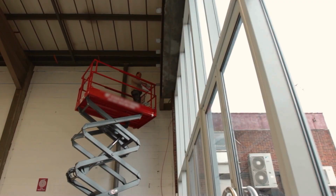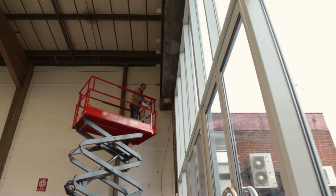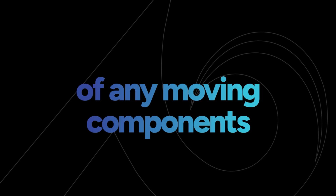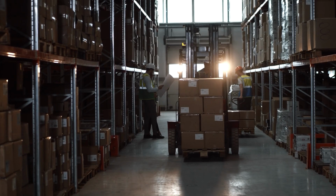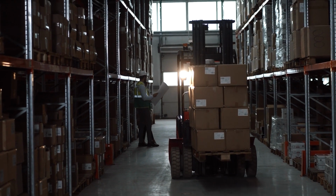When the scissor lift is being extended or lowered, the area around it should be cleared to prevent crushing accidents within the mechanism. Body parts, loose clothing, and tools should all be clear of any moving components at all times. Ground guides should be used when operating or moving the scissor lift. The scissor lift and another vehicle, like a truck or forklift, shouldn't be moved at the same time.